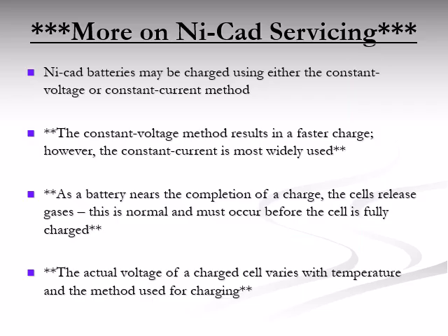Let's take a closer look at some additional aspects of nickel-cadmium battery servicing. NiCad batteries can be charged using either the constant voltage or constant current method. Although the constant voltage method charges the battery faster, it is the constant current method that is most commonly used in aviation due to its control and consistency.